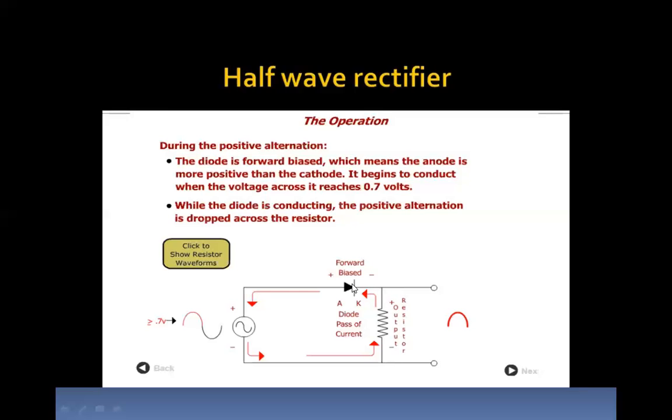It means when P-type material is connected to the negative polarity and N-type material is connected to the positive polarity, it is a reverse bias condition. And as we have studied, in the case of reverse bias, there is no current in the circuit. So that's the reason the output in the half-wave rectifier will be only for the positive cycle of the AC signal. For every negative cycle of the AC, the only diode we are using in the circuit will become non-conducting. It means there won't be any current for every negative cycle of the AC. So that's the reason this is called a half-wave rectifier.